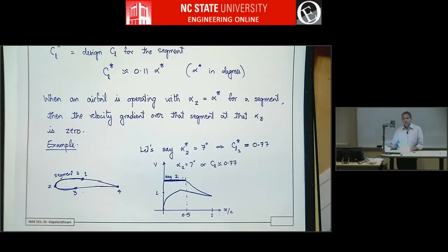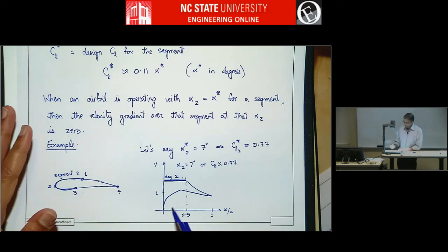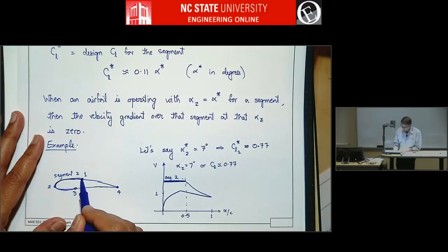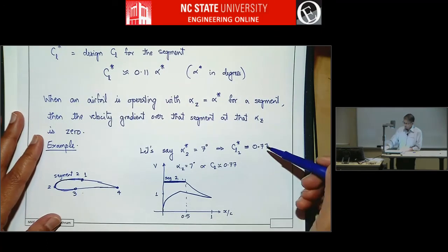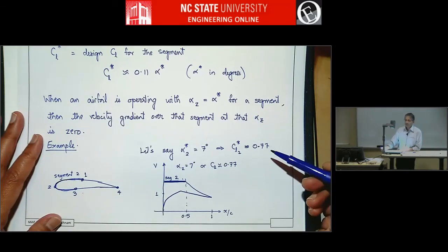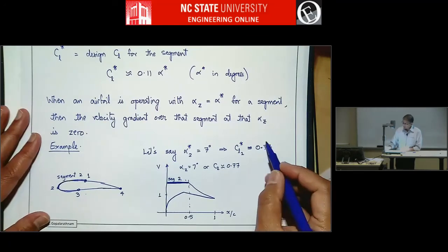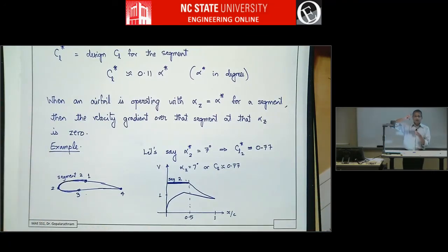So it roughly tells you, it will depend on the Reynolds number, but you can calibrate that pretty easily: if you take this airfoil, run it in Xfoil, then make a change and run it in Xfoil again, you'll quickly get used to that. So that's essentially saying you're designing this part of the airfoil to have laminar flow up to 0.77 approximately, plus or minus a little bit. That again depends on Reynolds number. That will define the upper corner of the drag polar.